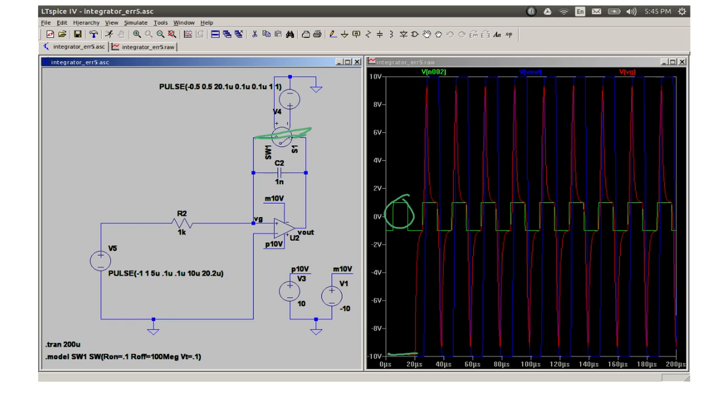so input is equal to output, and the output is now determining this node, and it sort of helps each other. This is positive, this is a large voltage with respect to this, it has a large gain, it stays at 10 volts. So these circuits will tend to get stuck in one state or the other unless they are forced to move from that state. So that's sort of what's happening. It woke up at minus 10 volts, helped itself, and then continued going to minus 10 volts, and it was stuck there. And you have to sort of force it.